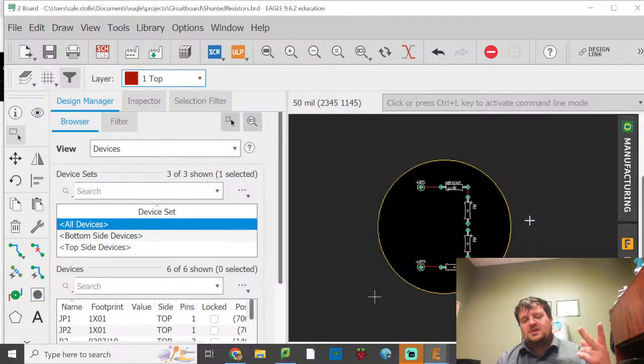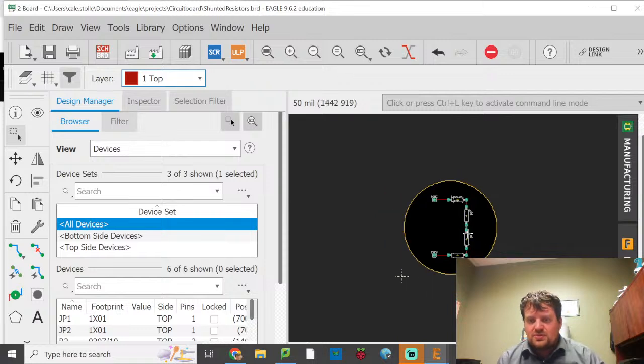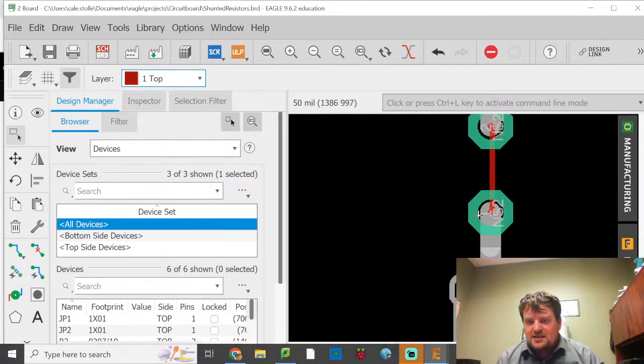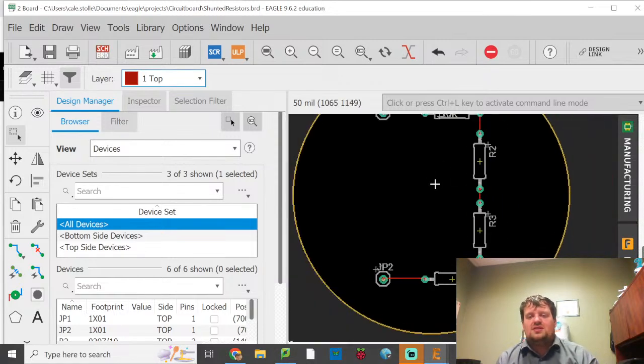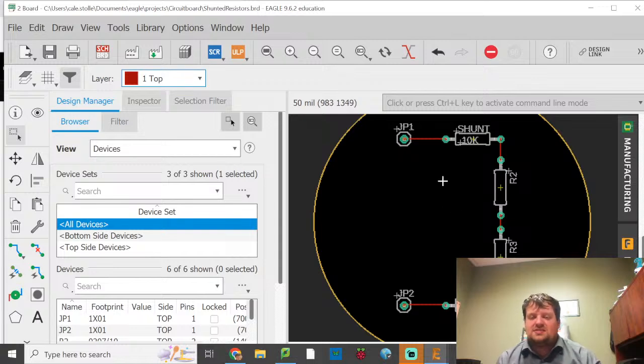So those two pieces, cutting out your shape, cutting out individual holes, so every one of these through-hole components, right here it has to cut out that hole, and then that green piece will be pasted in its place, which is just going to be the contact electrode for my resistor as I solder it in place. So all of that will be done with the CAD file, the CAM file.